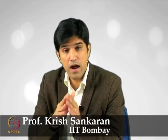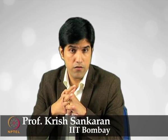We will try the same problem also in the case of the Poisson equation to see how the right hand side can be implemented in Matlab, and I would like you to see how you can manipulate the spatial discretization in the x and y direction, and also the number of iterations that we use. That way you get a holistic understanding not only about the discretization method and the differencing method, but also about the simulation parameters and their influence on the numerical result.